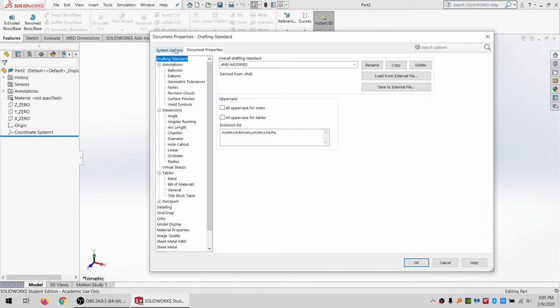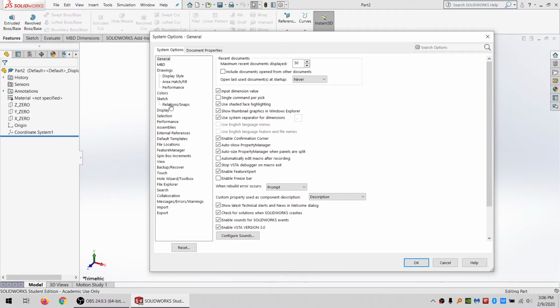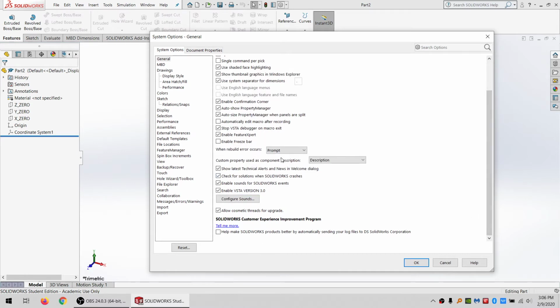So I was working over here. We can also work on this side, and there's a lot of settings that are useful to modify, so I'm just going to go through and point out some of the ones that are noticeable. Here's one that a lot of times if you're doing diagnostics or fixing other people's things, you're going to want to change this to continue, because you're going to have so many times that you've got a rebuild error, and maybe you've walked away from your desk or whatever and you don't want it to stop then.